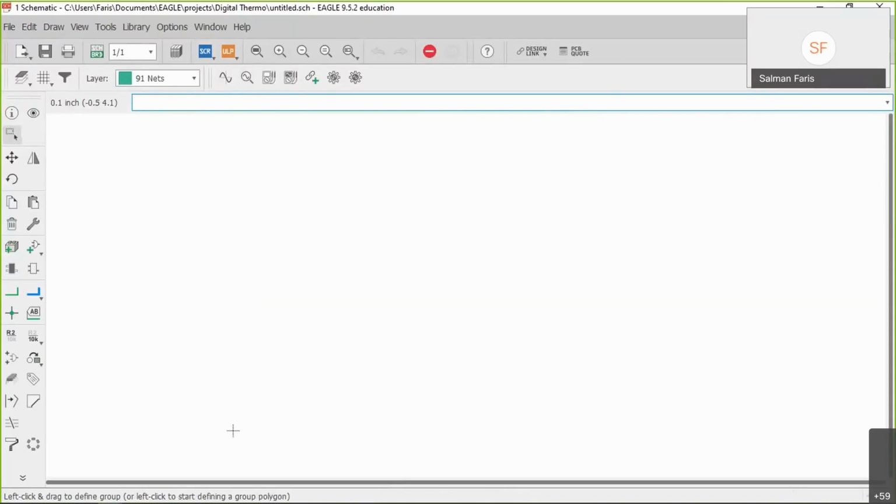So this is our work area. I'll give an introduction to the different kinds of tools. This is the command prompt. We can add some commands here. And this is a toolbar. You can get some toolbars here also. You can see different kinds of tools like move tool, copy tool, delete tool, add design block, add part, port, net, and different kinds of tools. Okay, don't bother about that. You just need to get started with some basic tools first, then you can master everything.